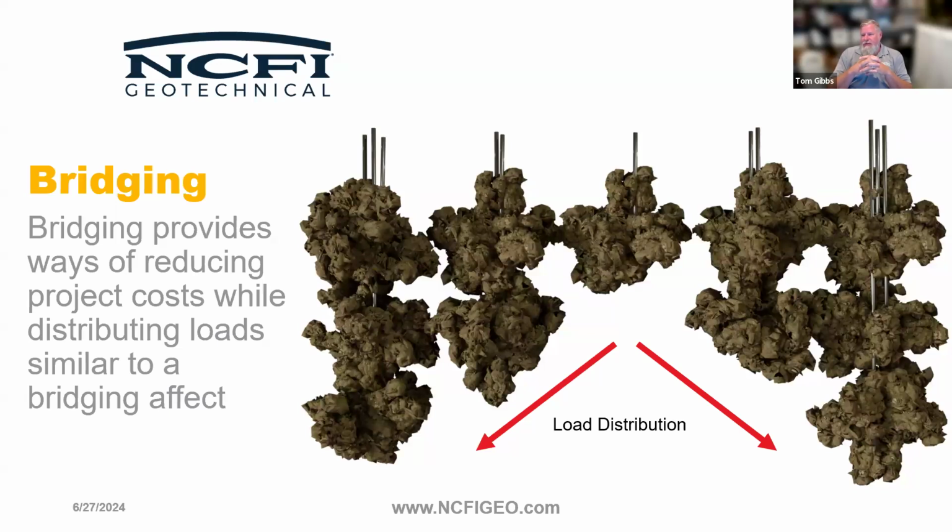So it's not something that's necessarily easy to measure. We have that data, but that's why we say you want to be using this product in soils that are soft enough that we're having a true effect. You could shoot this stuff into extremely compacted soils and turn it into a bowling ball. It would become so dense, but you're not really having a good effect there. There's not a great answer, but around 5 to 10, maybe 15 psi of expansive pressure in those soil conditions.